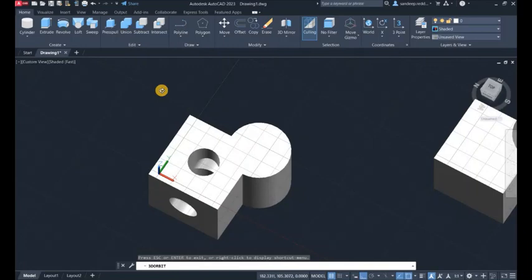So I still encourage you to go ahead and practice, because I have just touched briefly on each of the commands or functions in 3-dimension drawing, which is to change your UCS, to change your view to 3D, and to change the menu bar to reflect the 3D icons, much easier to access. And the major ones were modifying your solid, that is to union, subtract, as well as intersect.